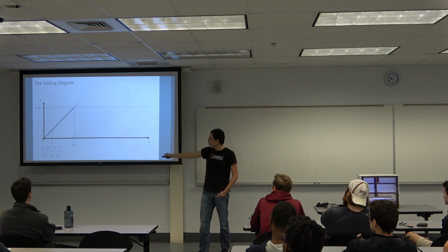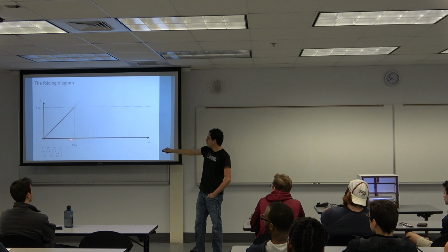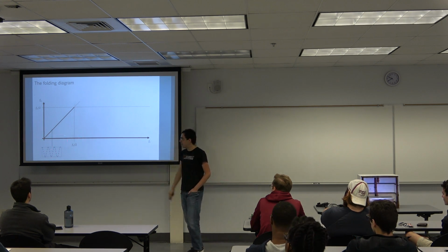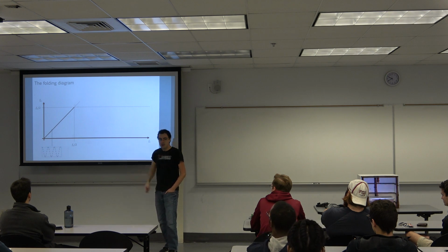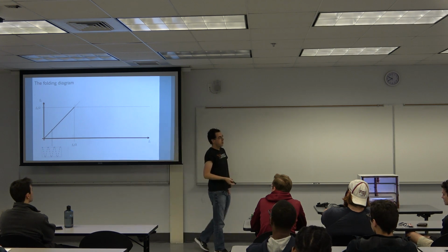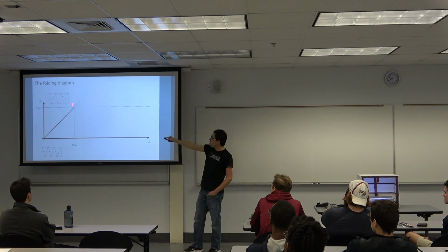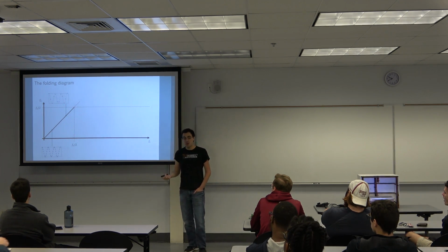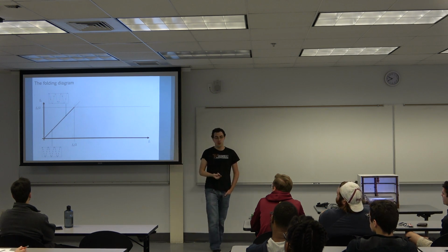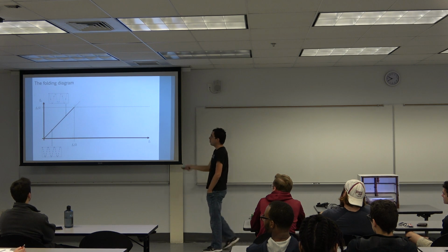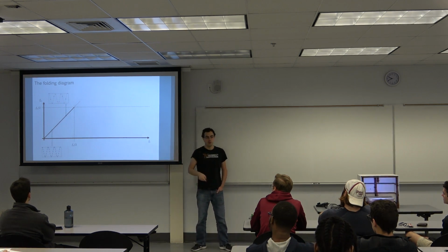And here is an example of how it looks if the true frequency of the phenomenon is low in comparison to half of the sampling frequency. We get a lot of samples, and then we can easily reconstruct the waveform. If we increase the frequency of the phenomenon, then we get fewer samples, but we still get a few samples per cycle, which allows us to reconstruct the phenomenon, assuming the phenomenon has only a single tone, which is actually quite important.